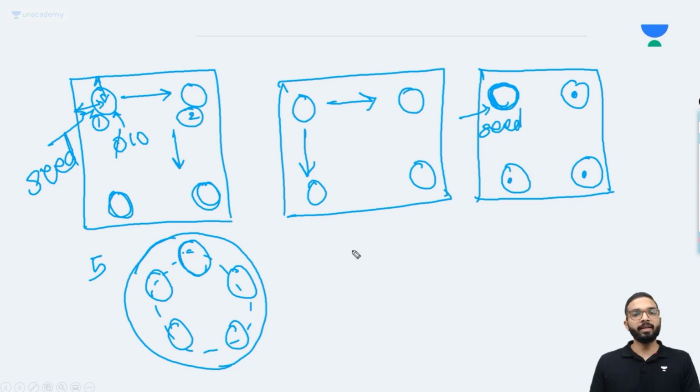In this module, we would be also learning about mirror. Mirror is also a special type of pattern. It is generated about a fixed plane. Let's say this is my geometry that I have created and I want a mirror of this geometry to be created. I will simply specify the plane about which I want to mirror and the part that I want to mirror. Once giving all the inputs, it will simply create a mirror of this part.